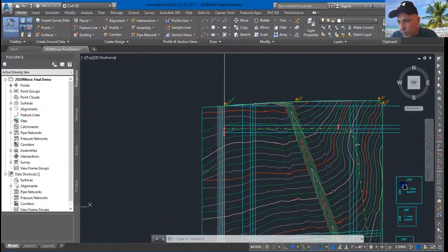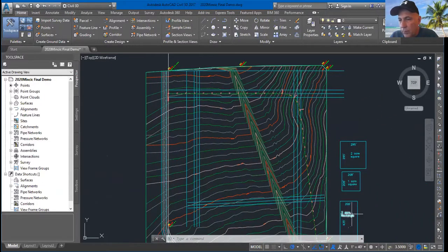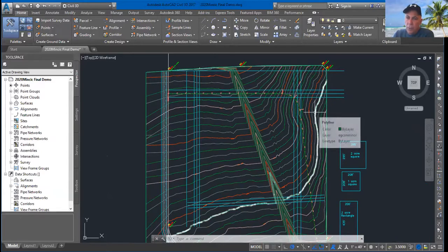Again, remember these cyan lines really were designed to give us a relationship of size. Also, we came over here and made our parcels, and our parcels had some distances attached so that we could see what exactly a 2-acre square lot was, and what a 1-acre square lot would be, and how that would fit along here. Now, we would have to know the subdivision criteria. In this situation, our client has decided that he wanted 1 and 2-acre lots, or something in between, 1 being a minimum, 2 being a maximum. So we're going to use that as our design criteria.